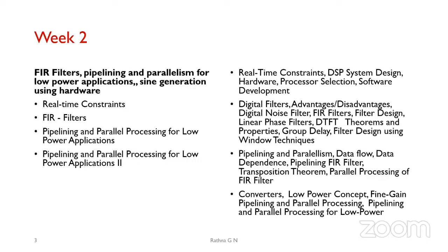So in this case, we went with the simple FIR filters. We said it is a linear phase filter. How it is linear phase, we have taken an example of a low pass filter and one high pass filter, and this defined it. The other things you can derive for band pass and band stop filters also.